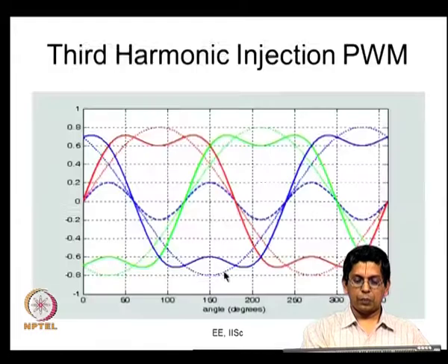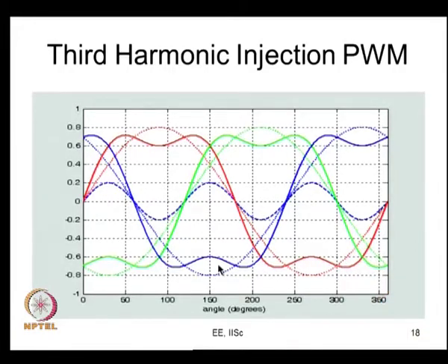Alright. So, now you go PWM method by PWM method. I said that this procedure is common for anything. So, it is not just sine triangle PWM. What I have done is, on this modulating signal, I have added a common mode signal to all the 3 phase modulating signals. So, your R phase signal looks like this. The common mode signal is a third harmonic signal. So, that is why I call this third harmonic injection PWM. We have seen this before. Now, what should I do? The duty ratio I must calculate based on that. What happens in the duty ratio?